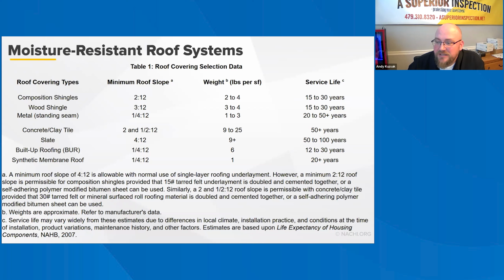While very steep roofs will tend to increase drainage efficiency, they increase the building and the roof's exposure to lateral wind loads. Furthermore, water flow velocity will be increased, especially in the valleys, which may cause scour, which is accelerated water, and overshooting the gutters. Also, very steep slope roofs are more difficult and less safe to access for construction, maintenance, and replacement.